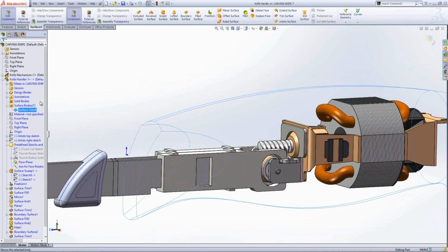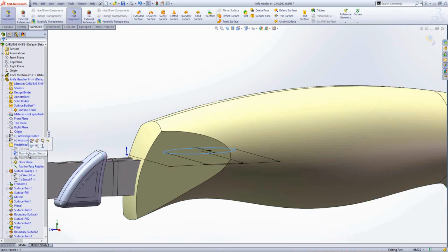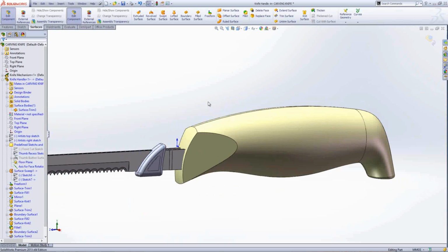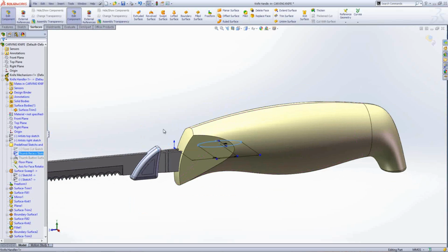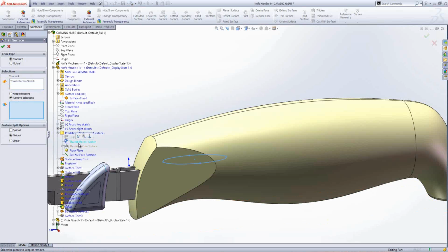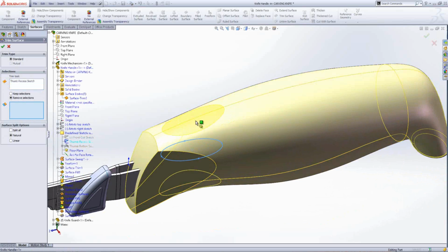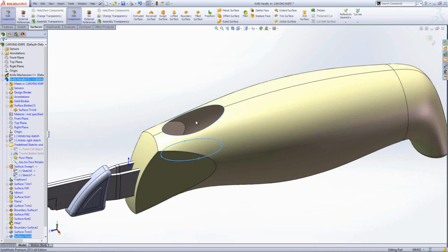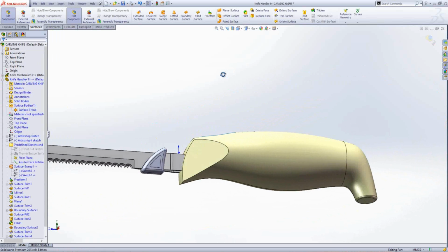So we'll just bring our surface back, and I've actually got a defined sketch for that, which we're going to use to trim our design. So if I just pre-select the sketch and the trim surface tool, we need to go back onto standard trim and just select our sketch again. I can then specify that I want to remove that section from our design like so.